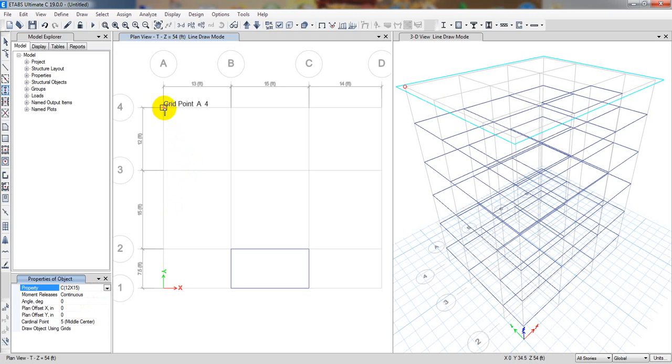our column, the length of our column is in the outer direction, I mean in X direction. Okay, and width is Y direction. So if you need to change that, you can change it from here, angle, that is the 30 degree, and you can use here 0 degree, you can use 90, then enter, and if you see here, it's a change, right?